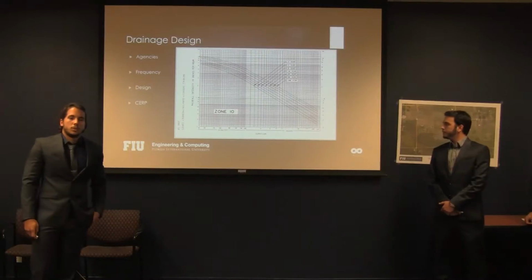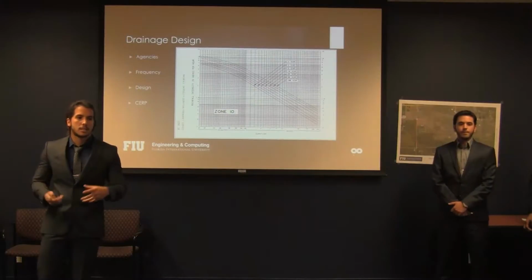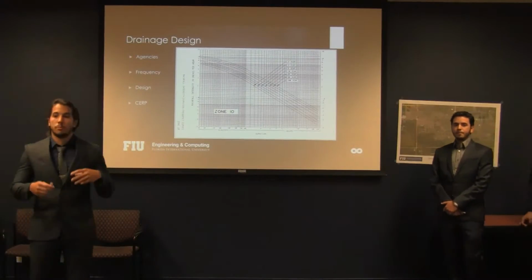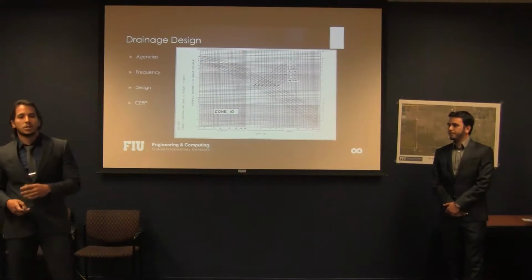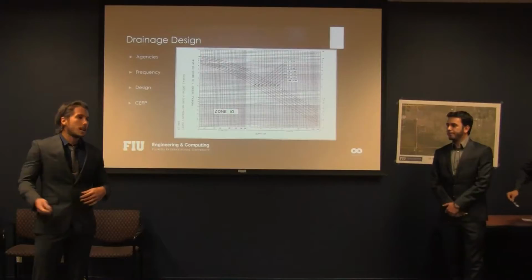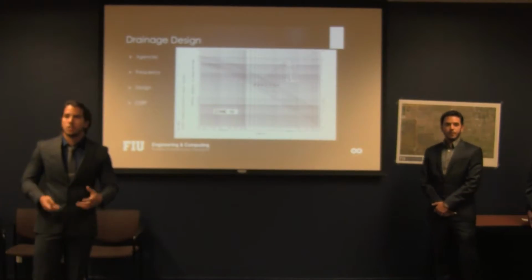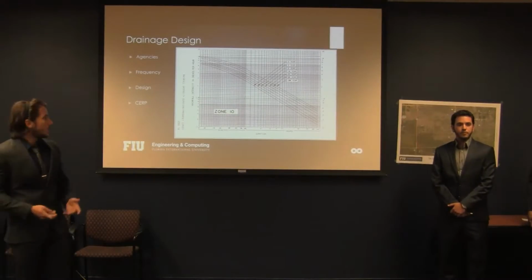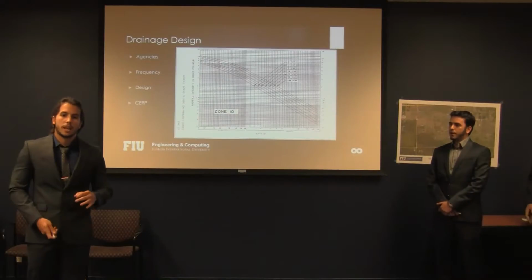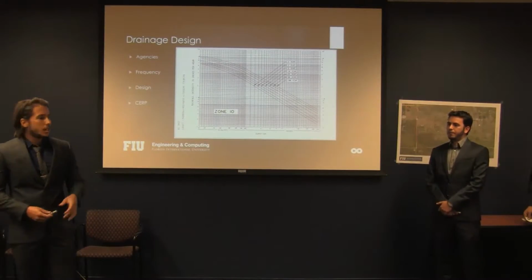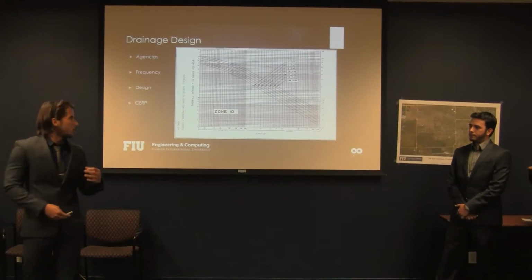First of all, Limitless Design has endeavored to create a system that not only maximizes runoff control, but also maximizes the water treatment capabilities. Why? There is currently an ongoing effort in the area to restore the Everglades as well as the wetlands. So we want to help, as engineers, go along with that effort and not hamper it in any way. Our design consists of a system of catch basins, French drain, and detention ponds. The French drain is to infiltrate the water, and the detention ponds are to remove pollutants and hold the water.